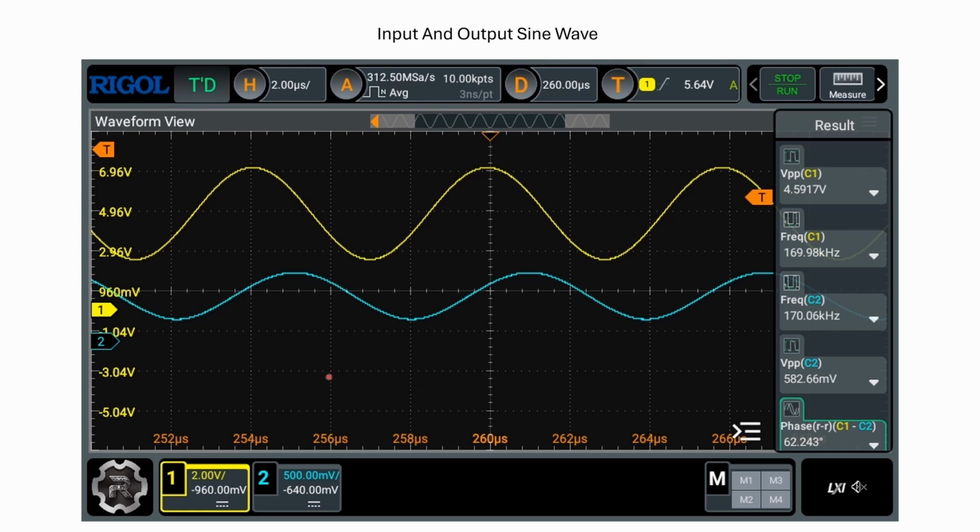Additionally, the amplitude of the output signal is significantly smaller than the input, suggesting attenuation, which is common in optical to electrical conversion due to factors such as resistance, capacitance, and light intensity variations. The smooth sinusoidal nature of both waveforms indicates a consistent and periodic response, typical in frequency-dependent experiments, where the photodiode's response time and sensitivity affect signal behavior.